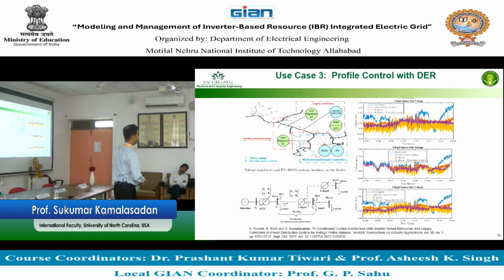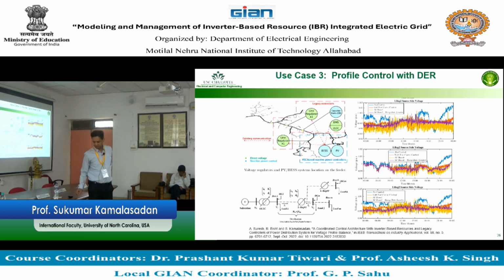So you can only survive in some conditions if you have hydro, sometimes wind, sometimes battery energy storage, hydro peaking as a mix. Just having PV and nothing else, with a 100% renewable target, you cannot operate the electric grid, you collapse.